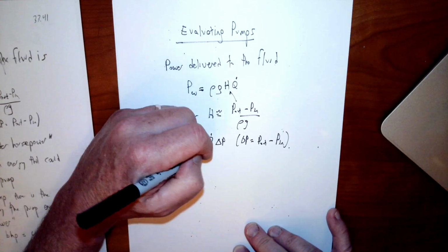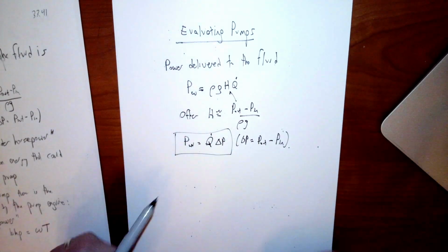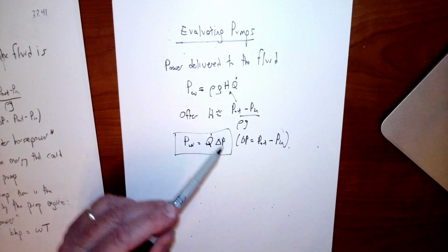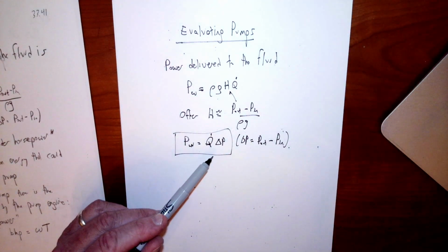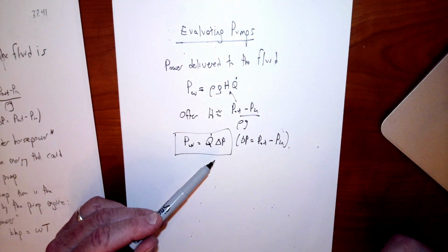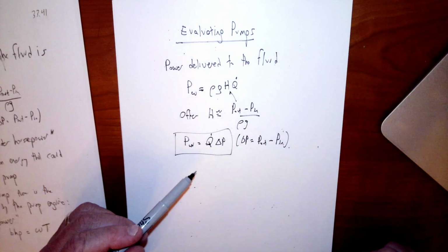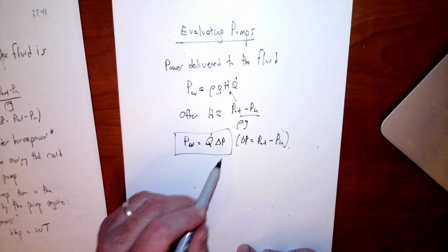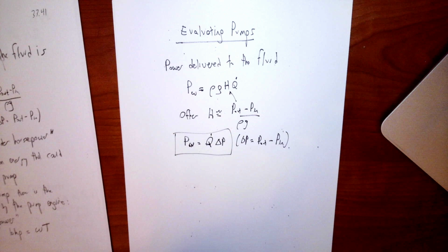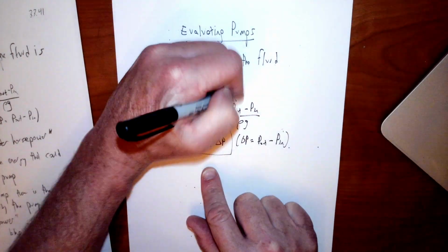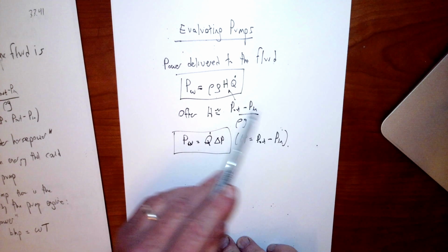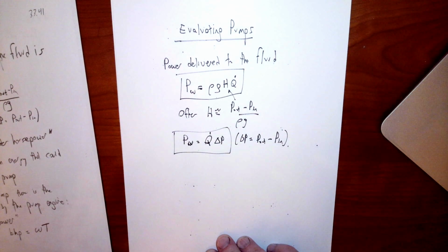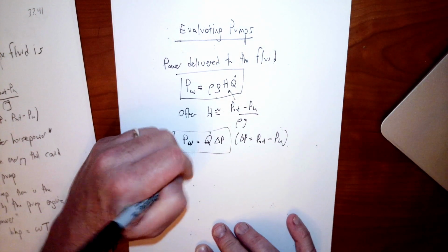So that's something we saw before, the minimum amount of power that could be delivered to the pump in order to achieve the result in the fluid. So this is the amount of power that's actually delivered to the fluid. Obviously, that's the minimum power, electrical power, for instance, that you could deliver to the pump. That would assume it's a perfect pump, of course, that it had no losses of any kind, no electrical losses, no friction losses. No such pump exists. But at least it's a minimum, you can get what the minimum is, and this is the same quantity that we saw before. So these two values are actually the same thing for that case where Z in is about Z out, and there's no significant change in velocity in the fluid.